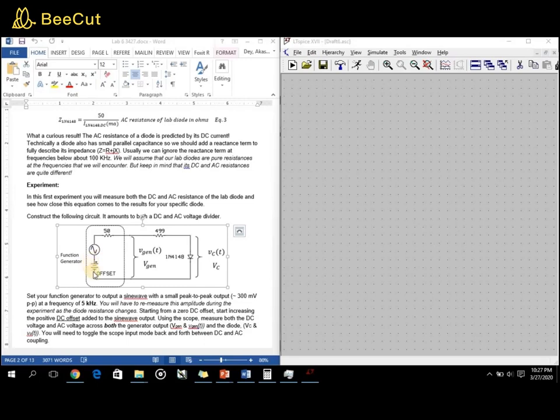However, in a simulator you could choose to have a separate voltage source providing that offset, and a different voltage source providing a sinusoid, and a different resistor being treated as an internal resistance. Or you could also have just a simple function generator kind of thing which combinedly gives you the offset, the sinusoid, and the resistance.